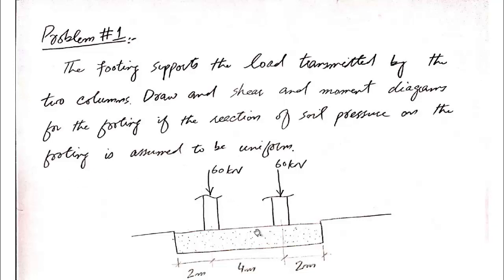So we are assuming that these two point loads are generating uniform pressure under the footing. We will have to calculate how much that pressure is, and then considering that pressure as well as these two point loads, we will draw the shear force diagram and bending moment diagram.